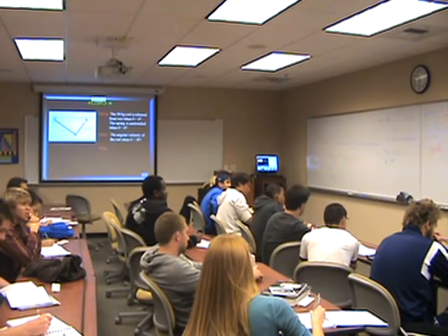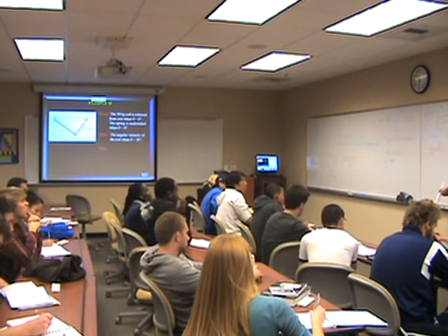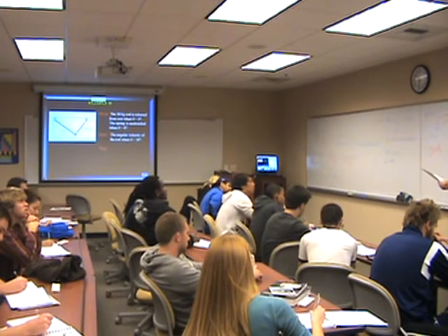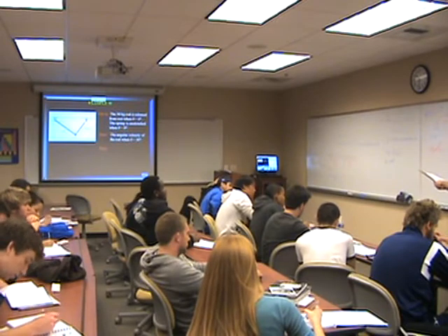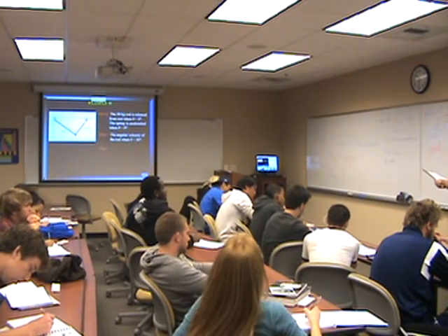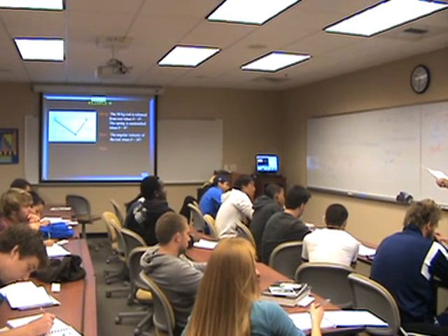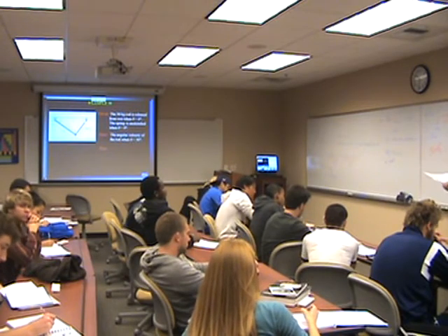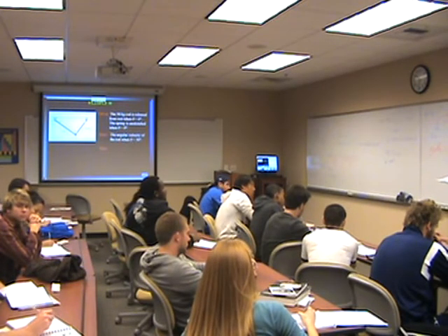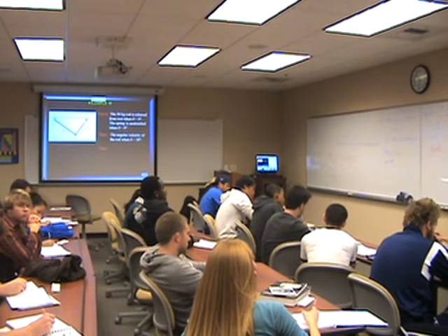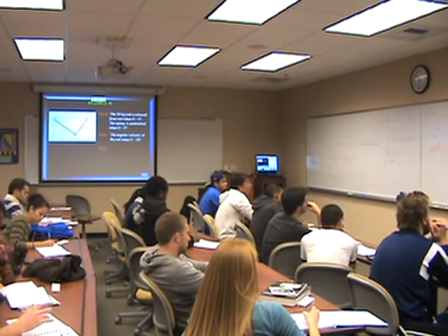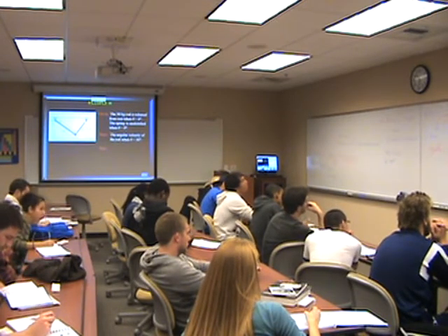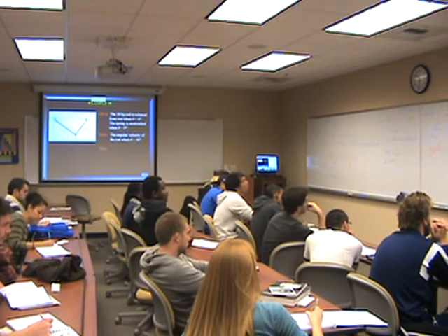What's that going to be? It's our mass times gravity times height. Mass is 30 kg, gravity is 9.81 meters per second squared, and our h is negative 0.375 meters. So this is mgh. That's gravity, and it's negative, which means we've gone down.